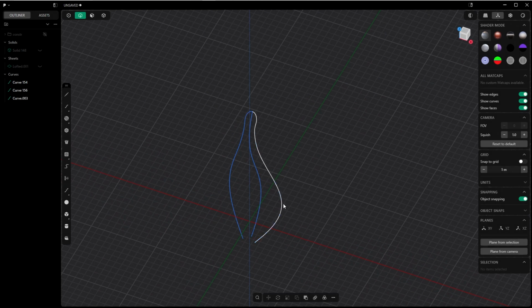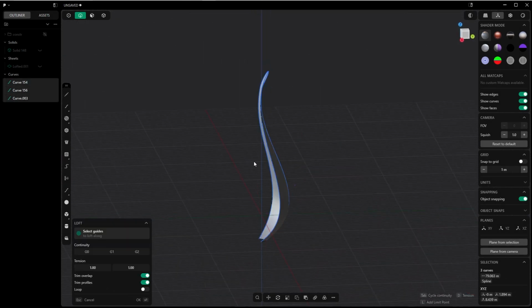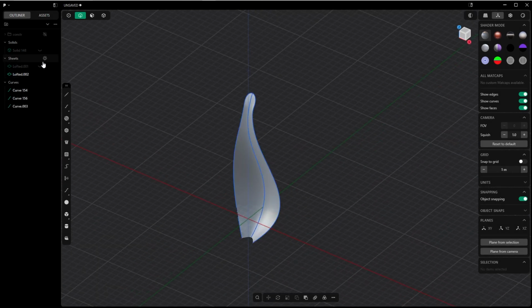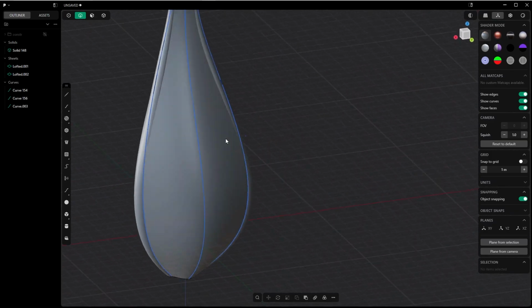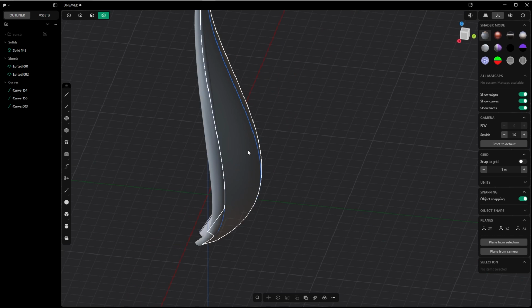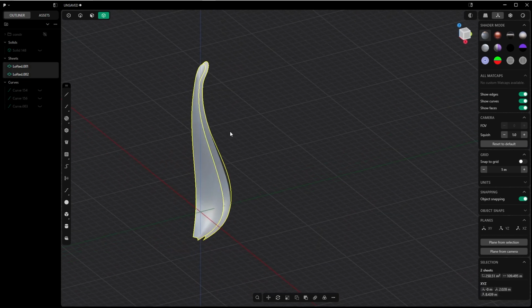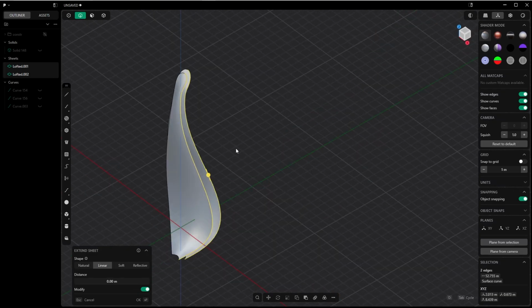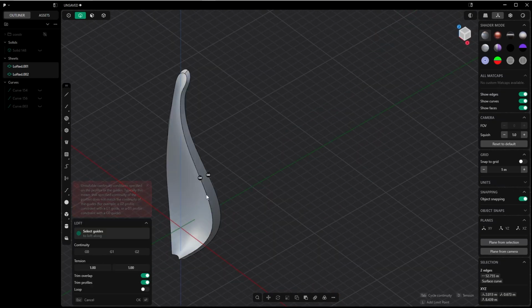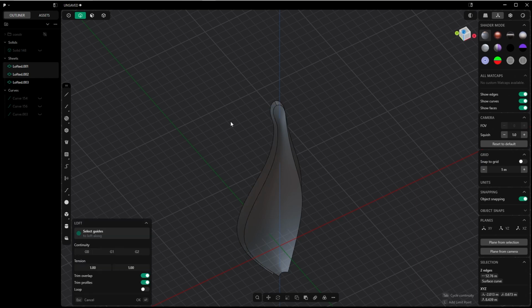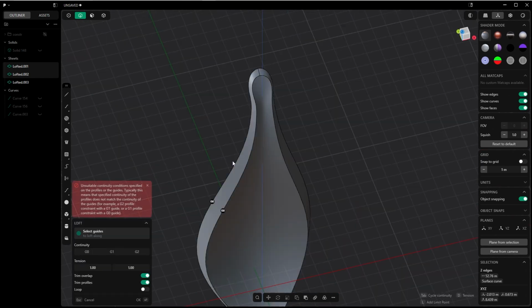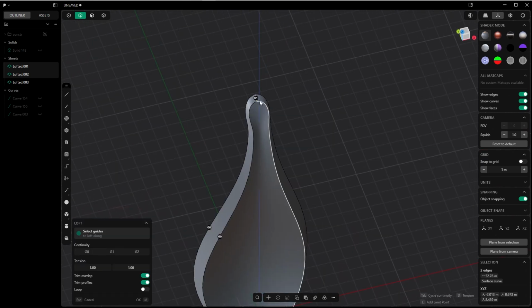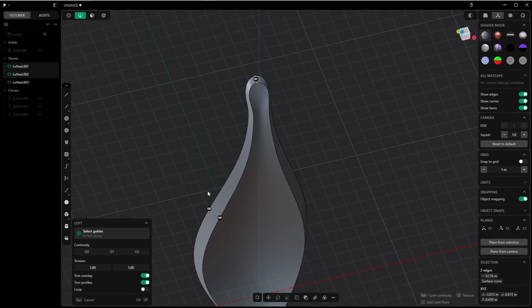Okay. We can loft, and it works. Press OK and bring back the sheet as well as the solid. And that's what we have. So select both sheets, Shift H, and let's turn them into a solid by lofting these parts with G0 continuity. Okay, I do the same here as well with loft and G0 continuity. And let's take this guy, but this one should be G1 continuity. So we have here a smooth transition.